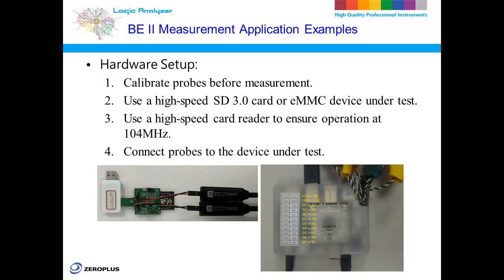Before measuring, it's critical to calibrate the probes. This step is essential for accuracy, ensuring that the results are not impacted by environmental or equipment issues. When connecting the probes to the measurement system, ensure they're positioned and contacting correctly. Improper calibration can lead to signal deviations or inaccurate measurements, so it's essential to calibrate the probes before each test.